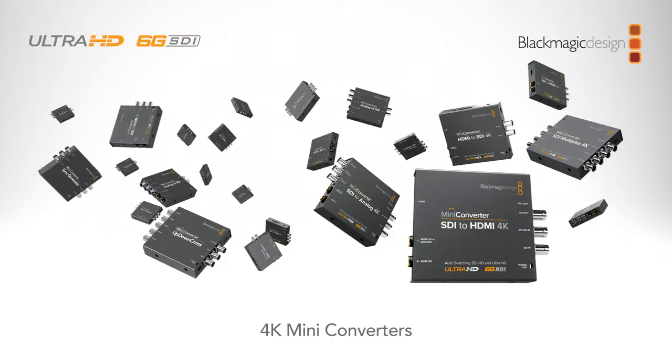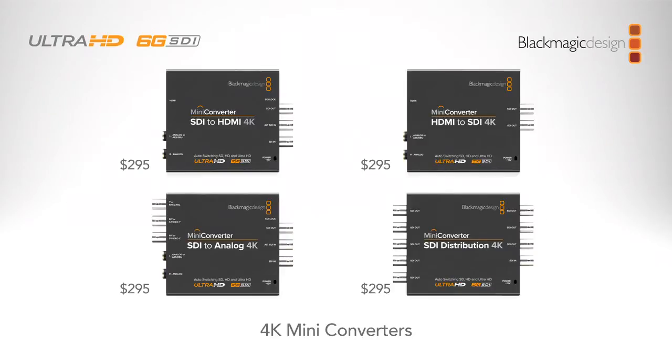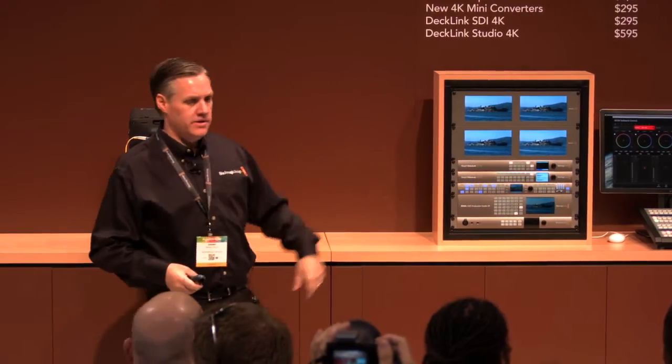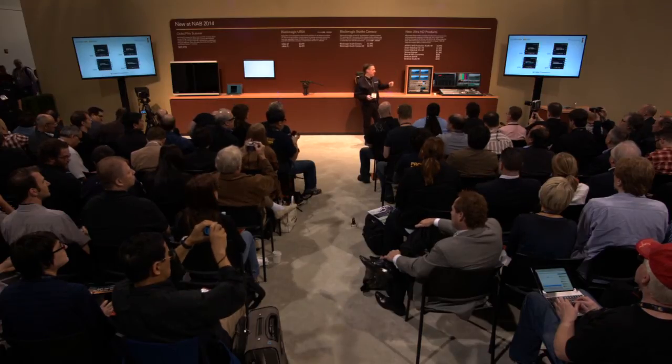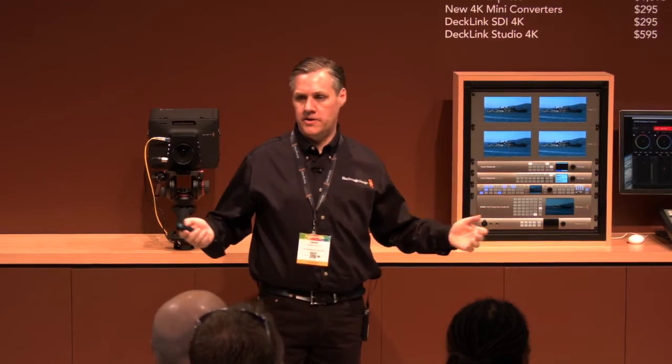We've got some new mini converters we've updated as well. We sell a lot of these, and we've added 6 gig SDI to them, so they can do SD, HD, and Ultra HD. They're the 4 models now, so we've almost got all our mini converters doing Ultra HD and 6 gig. They're $295, so they replace the previous models, and they've got down converters in them. So like obviously an SDI to analog converter, there's no analog Ultra HD, but if you're going to composite or component, it'll go to either HD or even composite all the way from Ultra HD. So really nice, you know, you get to a venue and they've only got some composite video projector or whatever in the facility, you can still feed your Ultra HD program feed from your live production into it because it'll down convert it.